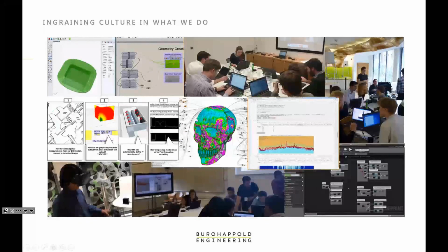Imidio, I think, was the driver of the hackathon that produced this funny shaped skull in the middle, and the intention of the skull was to test the limitation of the FE meshing and solving of Robot. But also, when you watch the video of the session they recorded afterwards, it's got a load of really useful information about understanding the basics of finite elements, the aspect ratio of the elements and the predictability of the results within those elements.